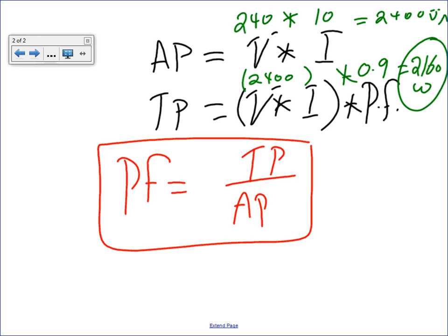And that's okay. 90% is okay. Look at my potential use: I can go up to 2400 watts by correcting the power factor. But I can go as low as utilizing only 2160 out of my 2400 allowance, and I'm okay with that. 90%. Any questions, guys, about the power factor? This is really the most important part of the whole presentation here.